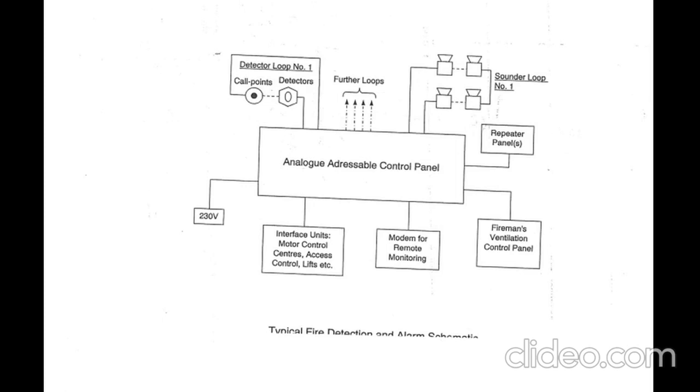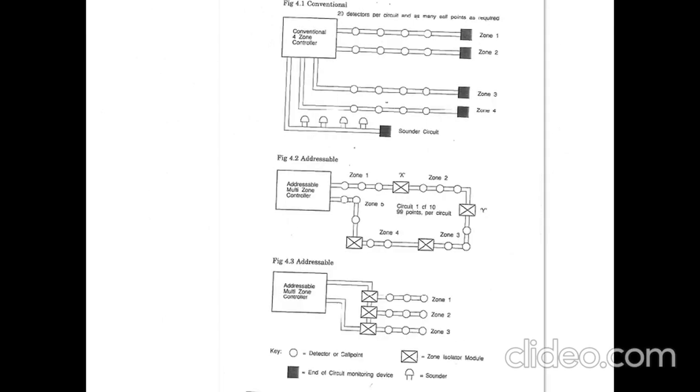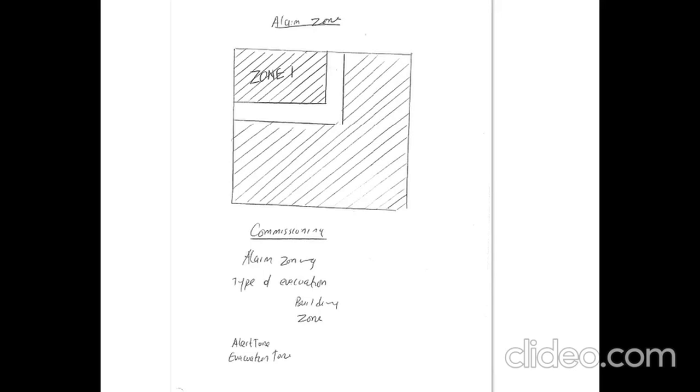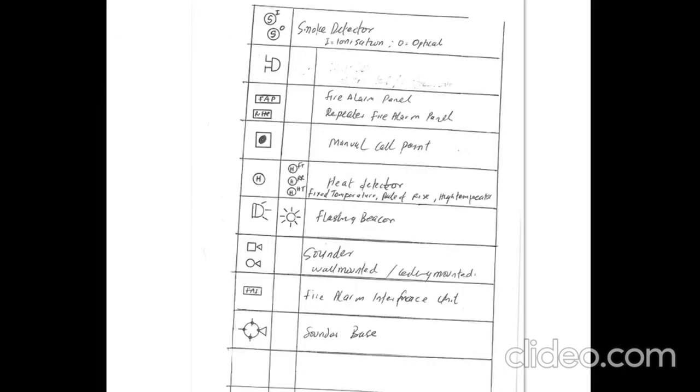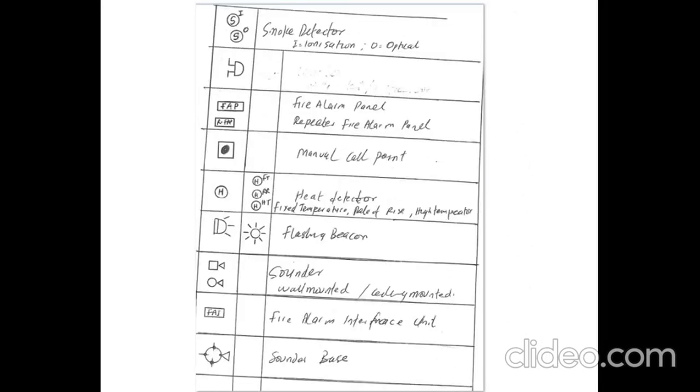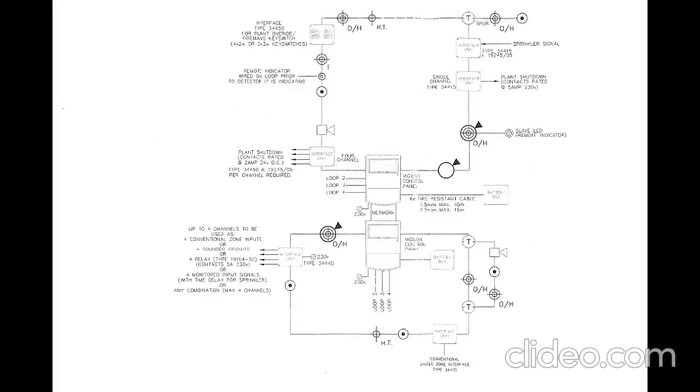So the third thing you've got to consider is siting the detector on a ceiling. When you are siting the detector on the ceiling, you must consider the closeness of that detector to downstand beams, to shelves, the closeness to the wall, closeness to luminaires, closeness to other services on the ceiling.